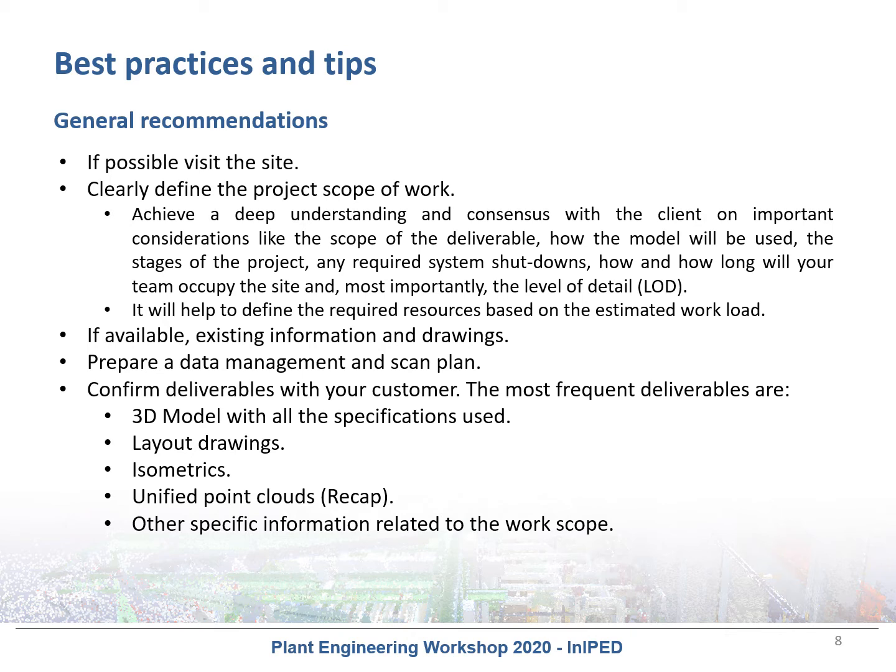Depending on how the model will be used and the level of available information, you will fix the level of detail of the as-built model and the deliverables with the customer. Meanwhile, you can see the scan locations in order to prepare a scan plan and define the multiple scan methodology you will follow.